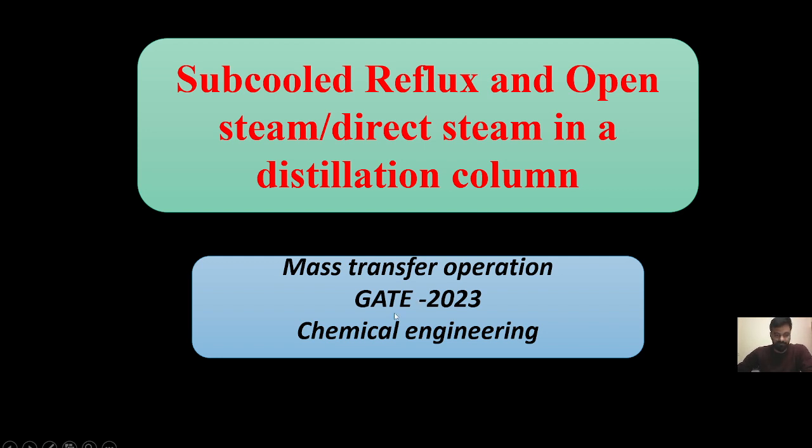So, my dear friends, in general, the reflux which is going to enter the distillation column should be at its saturation point. Okay, right? That liquid should be at its saturation point. But sometimes it doesn't happen to be at the saturation point. So there may be some deviations or some circumstances that arise, so that the reflux may be subcooled.